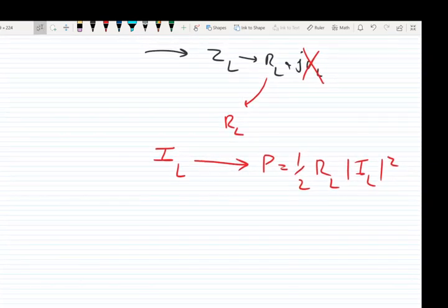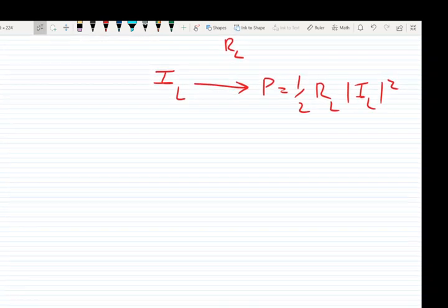The last thing I want to tell about the power is that if you remember, when we have a circuit, in order to find the total voltage or current at any point, we can use superposition. But for powers, when a circuit contains two or more sources, superposition applies only to the total load current and not to the total load power.